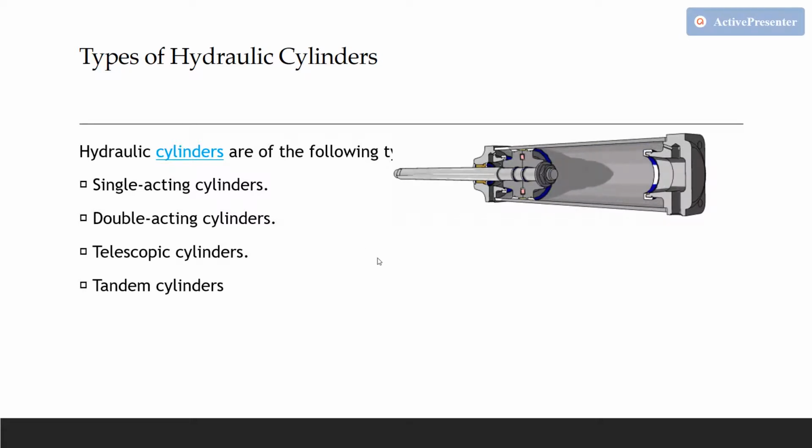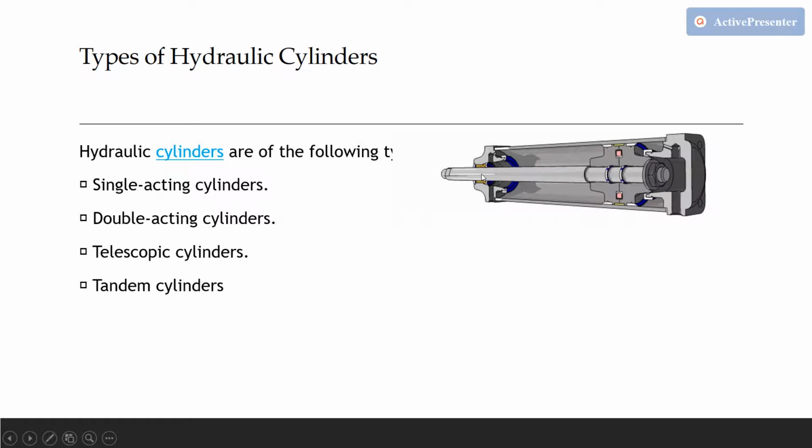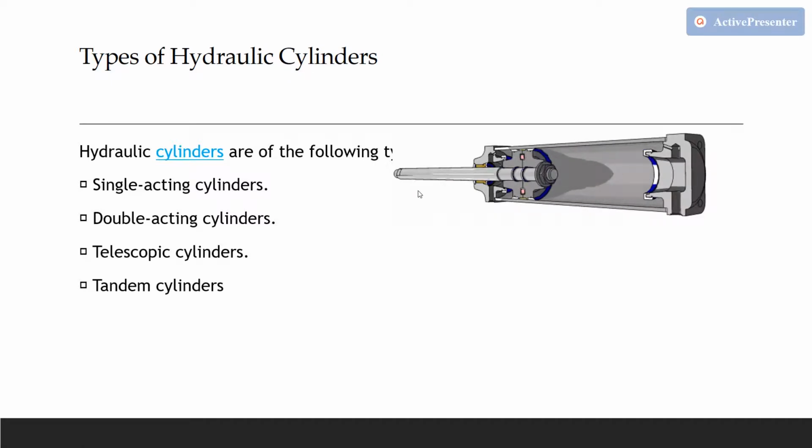The hydraulic cylinder, as shown, can either extend or retract a piston rod to provide a push or a pull force to drive the external load along a straight line path. Continuous angular movement is achieved by rotary actuators, or generally hydraulic motors.